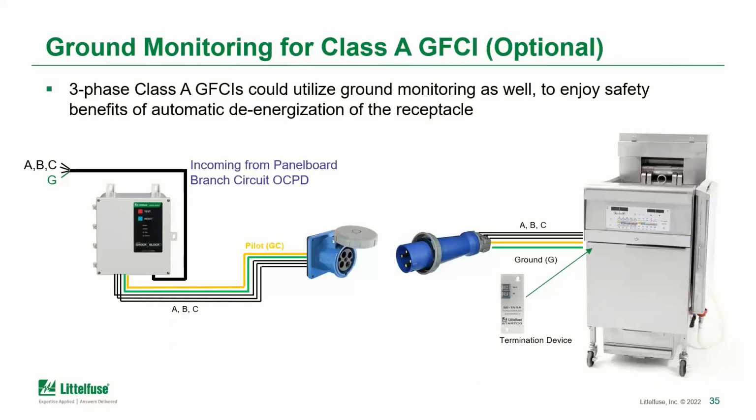And one final note on the ground monitoring part is that of course, it's not anything that's mandatory for the Class A GFCIs, but it's also something that could be used if someone wanted to implement it. So there's no restriction in the Class A GFCIs against using the ground monitoring. So again, there could be some types of equipment, and here we show a fryer, that could benefit from that automatic de-energization of the receptacle.